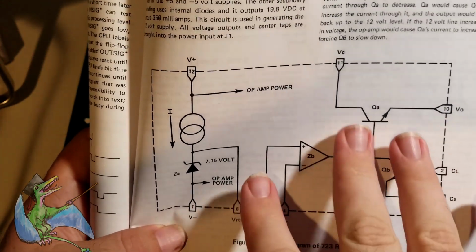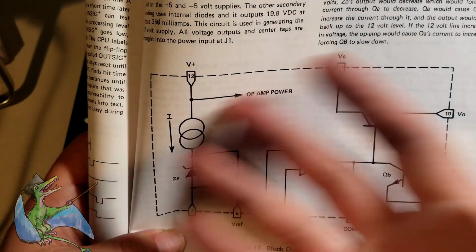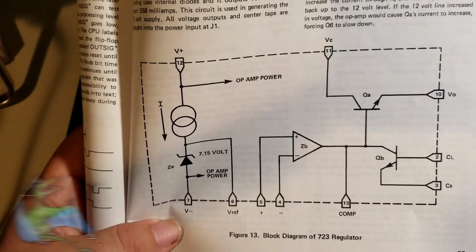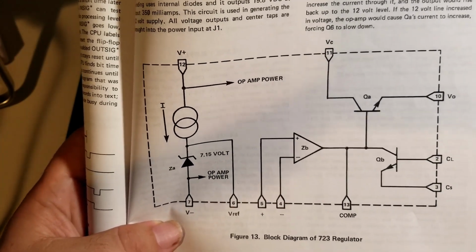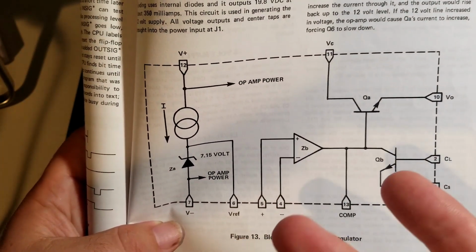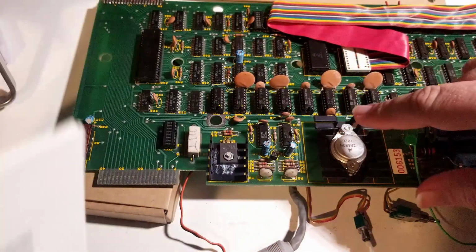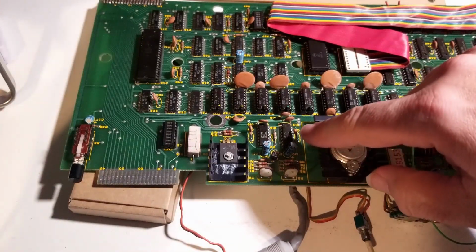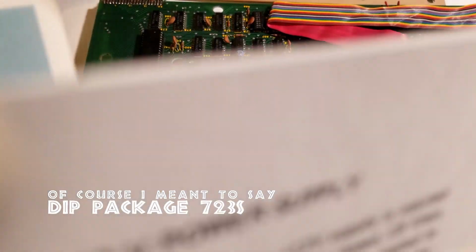Like if you open up a Commodore PET and look in the voltage regulator section, or even machines older than this, in an S100 machine, every card has its own power regulators on it. It's usually a 7805 and a 7812, which is just one can. This uses these two little black ICs right here, which are DIP format 7812s.